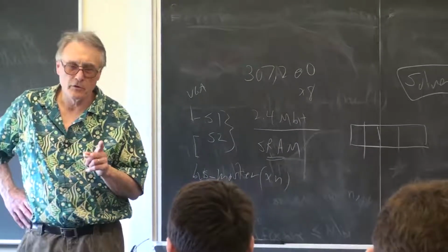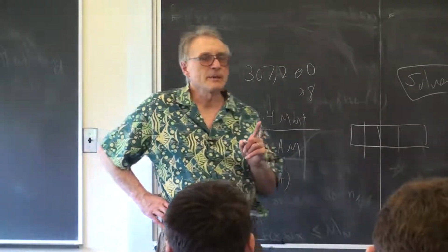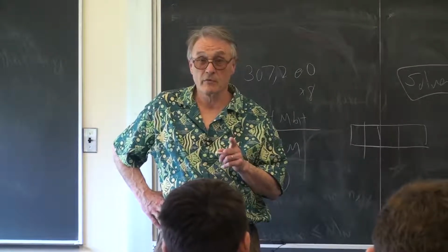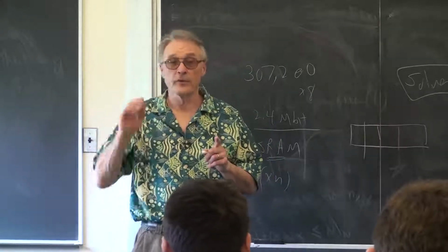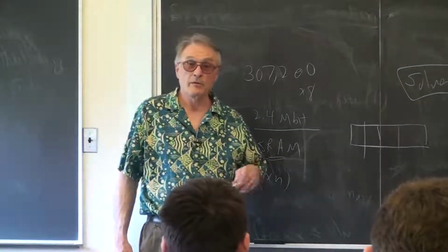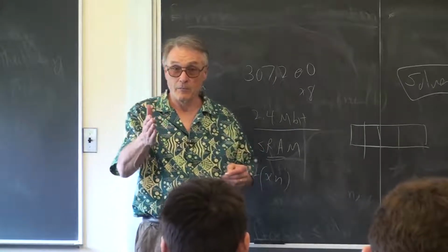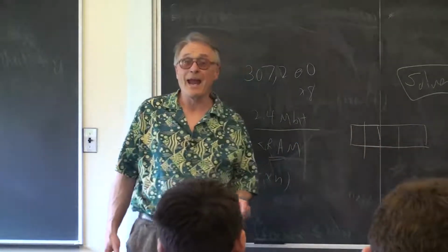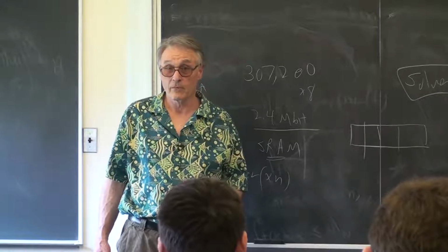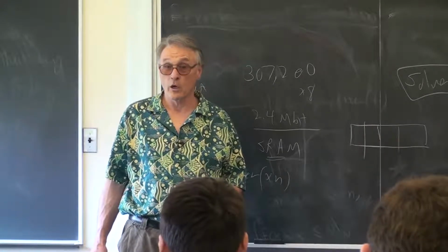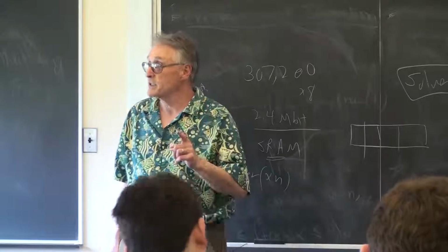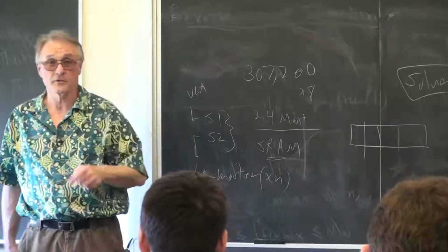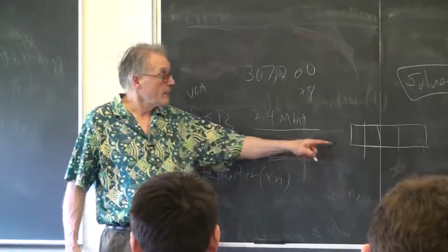I think what you need to do is when you set up the bus master, there's an address range and a width that's associated with it. And I think if you set up the width to 32 bits, that it will do the obvious thing. First of all, you have to have now word-aligned writes, but it will write the 4 bytes into memory on the same bus cycle. So that might be a way of speeding up by a factor of 4 at the expense of making the solver a little more complicated. Because now it's going to do 4 pixels before it calls for a write.